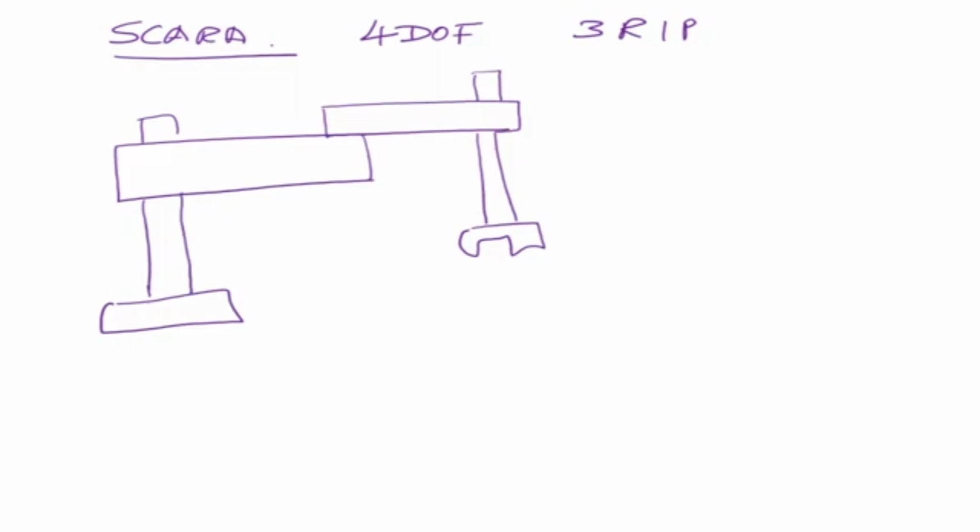So the first thing, what are the 4 degrees of freedom? And corresponding to that, we'll put our axes. So this is the revolute axis, like this. We can say that is my revolute axis here. We shall call this Z0, Z1. Z0 is the reference. We put Z0 and Z1 together to avoid one transformation. This is Z2. Let's see the origin there. Now the third axis is a prismatic axis. It is fixed onto this link here, and my axis direction is this side, but it's a prismatic axis.